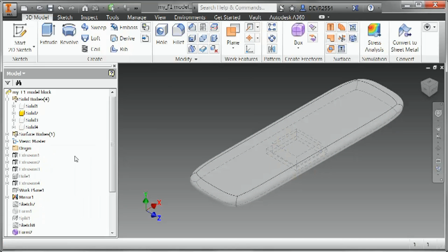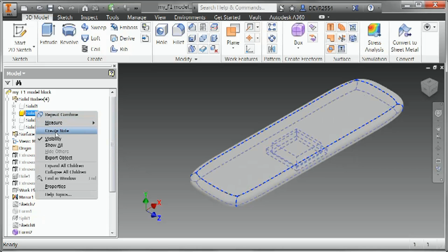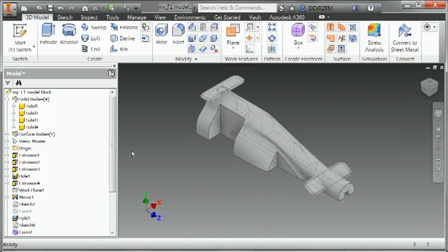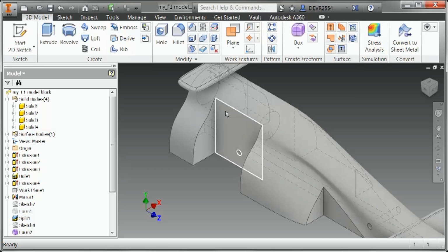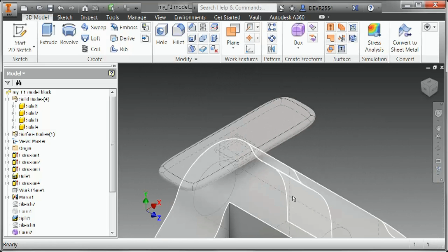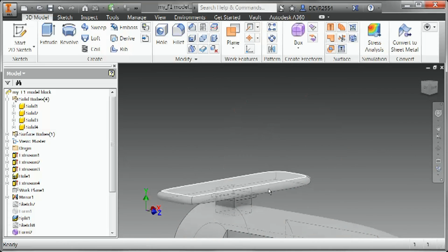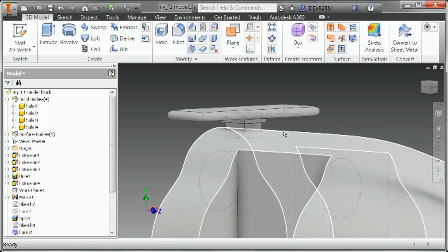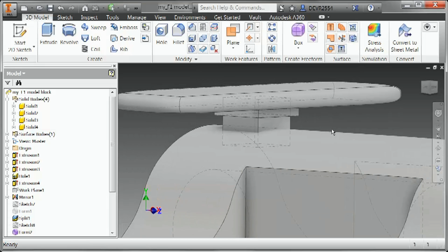So now the second extrusion is joined to the wing, and let me show you. Turn off that first extrusion, and you can see it just by itself now. So our design's coming together quite nicely. Let's review what we did here. We did quite a few things in terms of combining. We created a small extrusion with a collar. The small collar is now combined with the wing and the second extrusion. That first extrusion has created a hole in the rear wing, and there's a bit of a problem here.